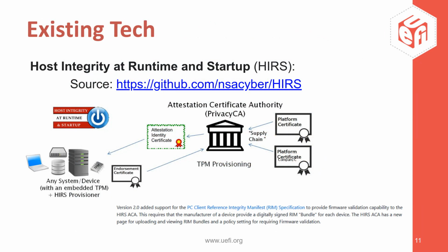So if we look at the existing technology that's available today, there is an open source tool that's been released by the US government, and it was initially released to validate TCG platform certificates, but that has recently been updated to support reference integrity measurements for firmware. It's the HIRS tool, or Host Integrity at Runtime and Startup.